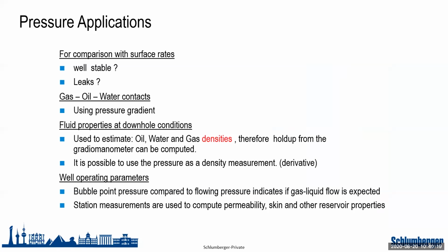So the pressure applications will be to understand if the well is stable, understand if maybe I have leaks in the tubulars, to understand the gradients in the wellbore in static condition due to segregation, and to be an input for my fluid properties at downhole conditions. So it will also be an input to the interpretation software, yeah?